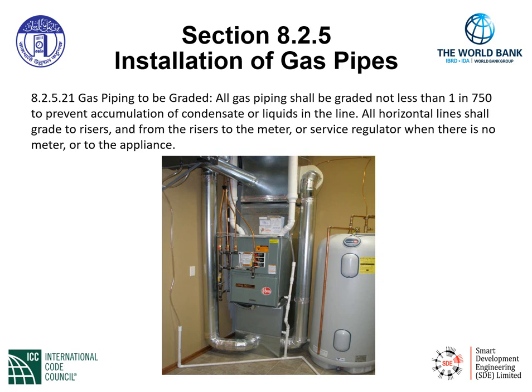We need to provide the pitch to these specific areas as indicated in this code section, such that we do not block the gas piping system from the desired flow and pressure as designed. Again, when you have wet gas systems, maintenance is of the utmost importance to provide drainage of these particular locations periodically.